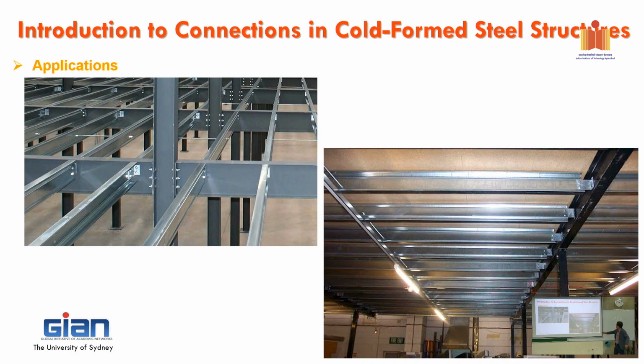Yeah, so we're trying to get to that situation where we just deal with the shear only. But then you can see that the panel will be subjected to a lot of shear problems, shear buckling, yielding, and a lot of other complicated problems, and instability as well, right? Easy for it to be unstable. Yeah. So very challenging, but that is typical. That is the nature of cold form steel. On both sides or only one side? Only one side. The clip angle is on only one side. Yes, only one side.